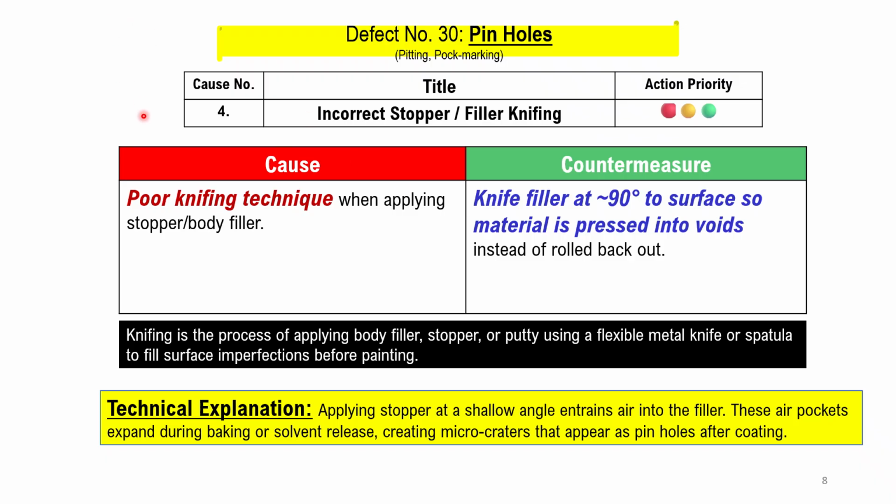Fourth probable cause could be incorrect stopper filler knifing. Poor knifing technique when applying stopper body filler. Applying stopper at a shallow angle entrains air into the filler. These air pockets expand during baking or solvent release, creating micro craters that appear as pinholes after coating.